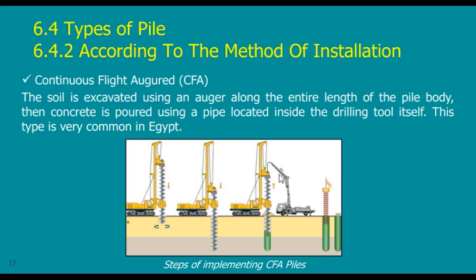This is if you are a superhero. But if you are not, then don't expect more than 50% of the length of the pile, or maybe it would just reach 4 to 5 meters and it will be stuck, because there are many reasons. You are not pushing a steel cage in water. You are pushing a steel cage in concrete, very dense concrete, and piles should be dense concrete. So you are trying to push it in a dense material.